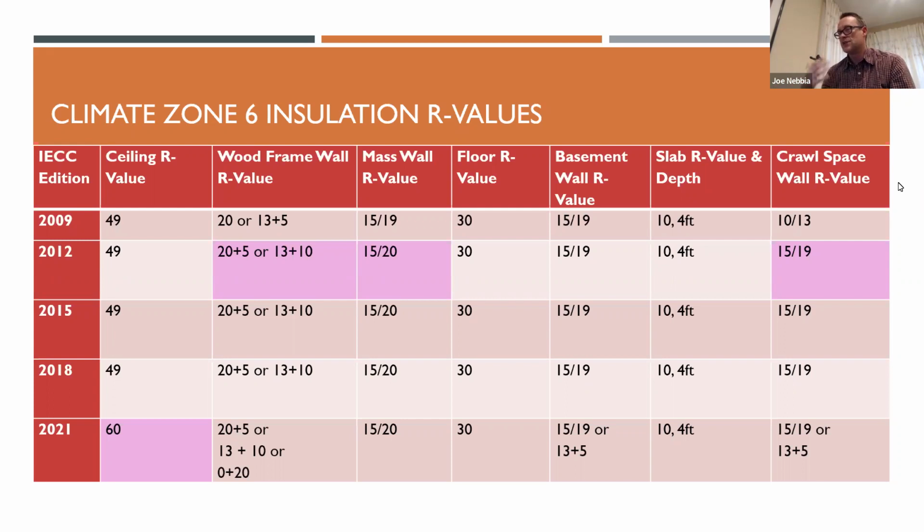So you're going to have to use the U value and calculate exactly what your U value is going to be in order to comply, rather than just an R value compliance. For mass walls, the next column, that's things like concrete block, poured concrete, timber. There's a lot of different things in the code that are listed as examples. ICF, insulated concrete form construction.